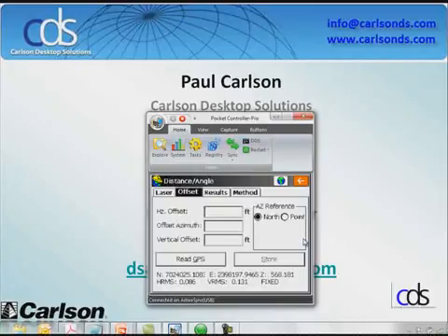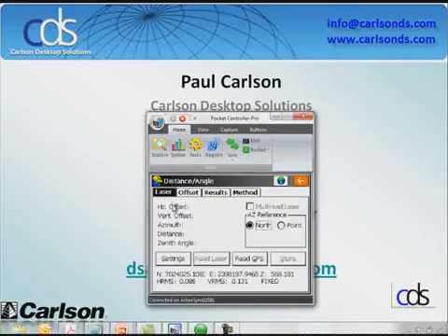What we ended up doing is connecting a laser rangefinder that had an azimuth or a compass built into it so it could display the azimuth. We would connect the GPS receiver into one port on the data collector, the laser into the other. You drive along, you get your GPS position, and then you say, I'm going to use a laser for the offset. So I lean out the window, I shoot the laser at the power pole, and now I've got a point that's computed at that offset.